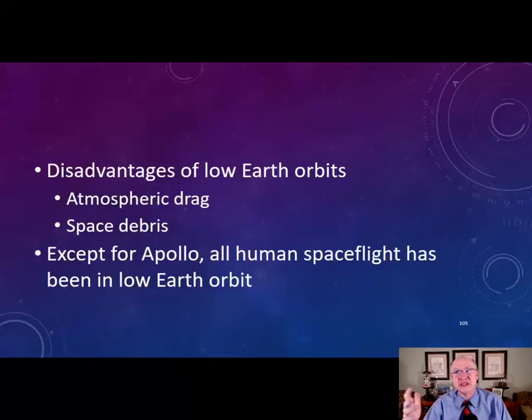For historic purposes and for contest purposes, we have a line that's at about 100 kilometers altitude. That's about 62 miles altitude. And some people will say that if you go above that line, you get your astronaut wings because we define that as the edge of space. And that's fine. They just had to draw a line somewhere, so they arbitrarily drew it at a nice round 100 kilometers or 62 miles. But the thing to know is that there's still plenty of atmosphere there. And in fact, satellites cannot orbit the Earth at an altitude of 100 kilometers. There's so much atmospheric drag that they'll be dragged down right away.